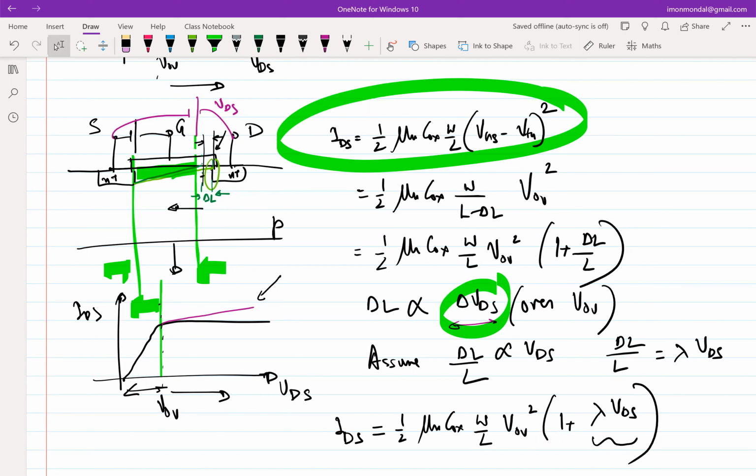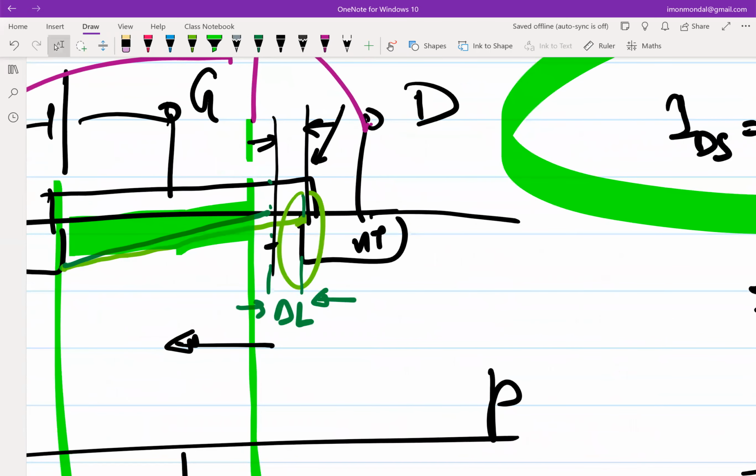So if you go back to that lecture where we talked about it, even though there was no channel, there was an electric field, right? So charges were available, the mobile charges were available in the channel everywhere, but for that junction. So now if the charges are available just at the edge and you still have electric field, the charges tend to be sucked in through that electric field. This is equivalent to a PN junction where you have a reverse saturation current.